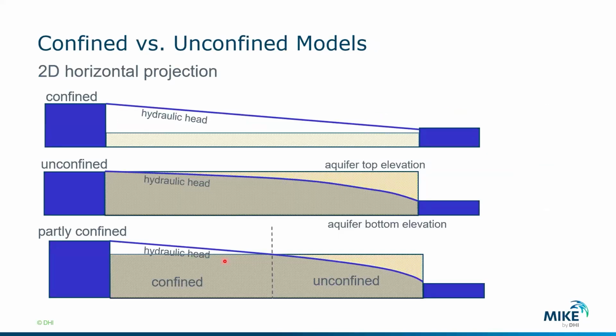And then we have these two base methods. Let's go back to the first one, what is called phreatic. And now we start adding a number of special cases. So we have these 3 possibilities. Either the system is fully confined, easy. So we solve the flow equation with a given hydraulic conductivity and heads.